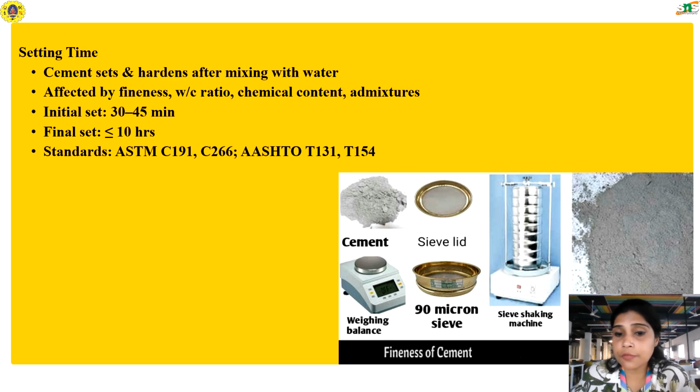Several factors influence setting time, including the fineness of cement particles, water to cement ratio, chemical composition, and the presence of admixtures like accelerators or retarders. For example, in hot climates, cement sets faster due to quick hydration, so retarders are often added to delay setting. On the other hand, in cold climates, accelerators may be used to speed up setting.